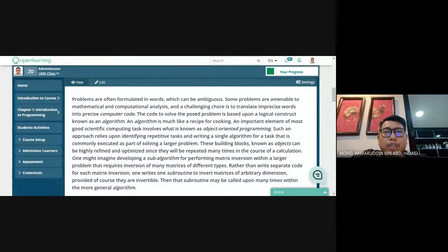Then you need to make sure that the degree of freedom is 0, which is the number of equations is equal to the number of unknown variables that you need to find the value of. So make sure it's zero. You will find out what the degree of freedom is, and why you need to do the degree of freedom analysis in order to solve the engineering problem.